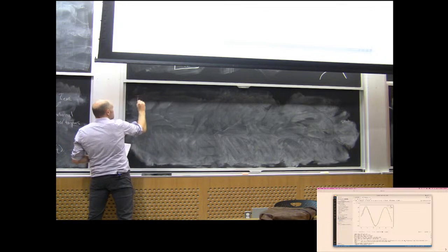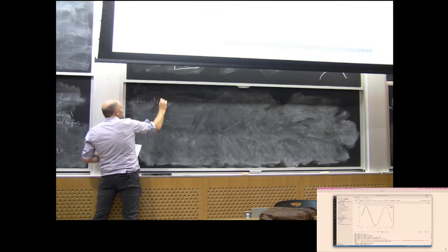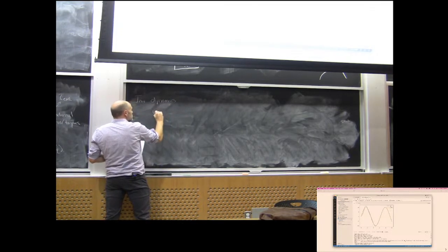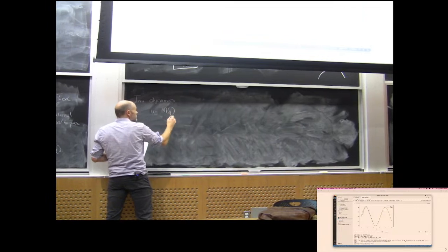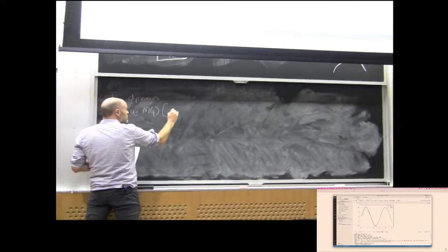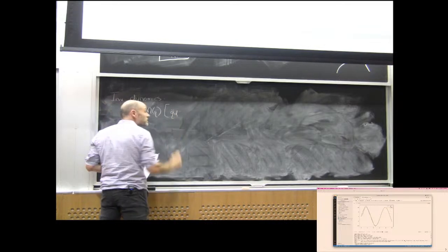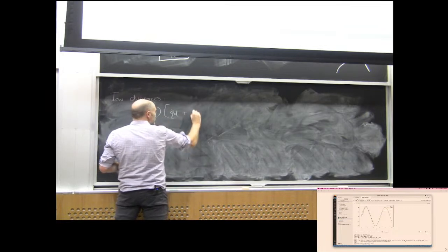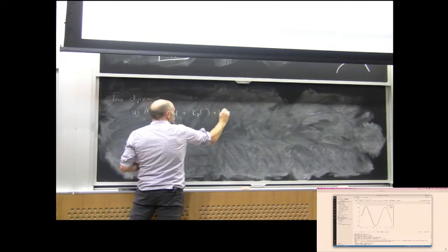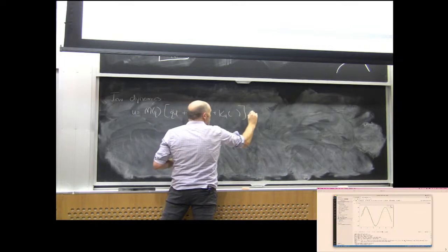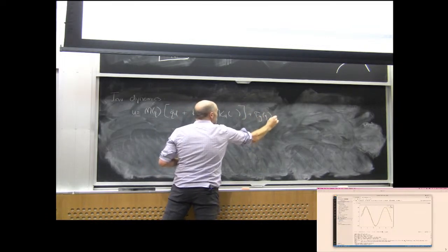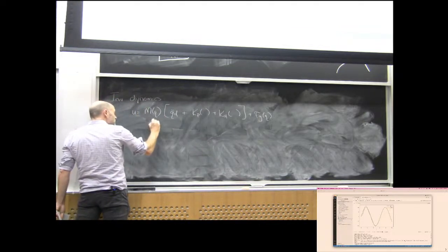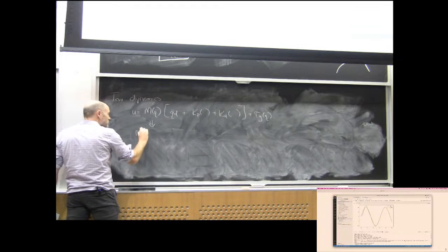The inverse dynamics controller would send in, I'm going to take a mass times the entire signal here. I'll send in q double dot desired as my lead, my feedforward term, and I'll put inside here my Kp plus Kd. Outside here, I'll take my tau gravity, okay? And the result is once again a beautiful system.